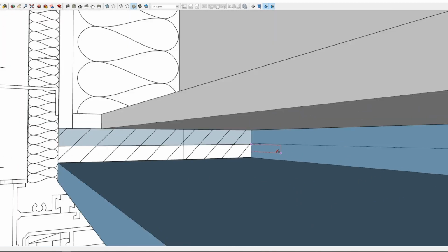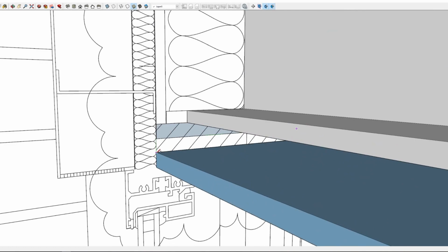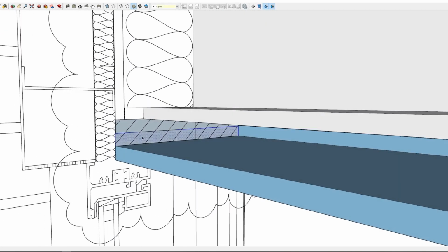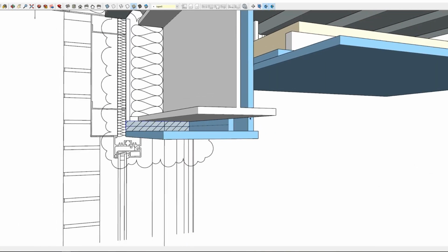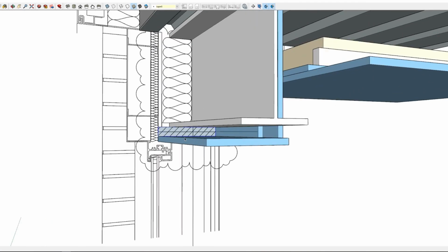And then what we've got under here is a couple of layers of fire rated plasterboard, and this detail, you can see the way it's clouded there. We haven't quite got to the bottom of this detail yet, but those 2 layers of fireboard will form what's called a deflection head detail. So there'll be a little bit, where the window hits the steel, there'll be a bit of movement.